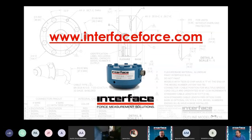Yeah, so you can expand that a little further. We have certain people who use load cells for impact testing. Then you might need to sample at 10 kilohertz. It doesn't matter how fast you sample the signal, because load cells can only respond so quickly as well. Typically a millisecond response time is typical. So you're not going to get an instantaneous response from a load cell, but it's relatively fast. There are no moving parts, and there's no active circuitry.